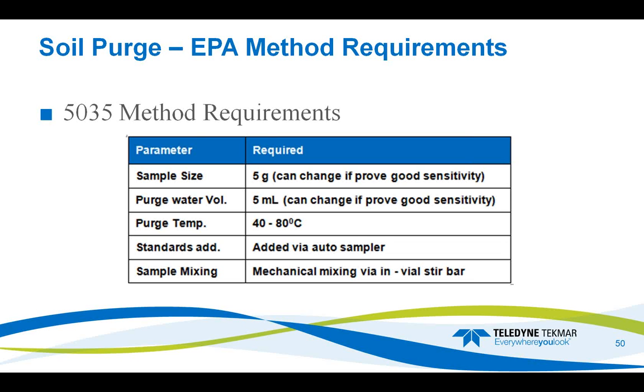If we get to amounts that are too small, are we really getting a representative sample if we're taking what ends up being a couple grains of sand or a couple clumps of clay? Is that really a representative sample of the whole soil itself? Our other issue is how full we end up filling our vial, making sure that our needle doesn't go below the surface of our soil and become clogged.